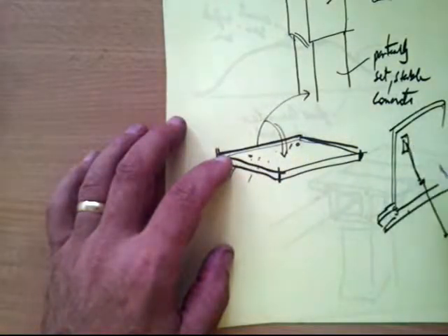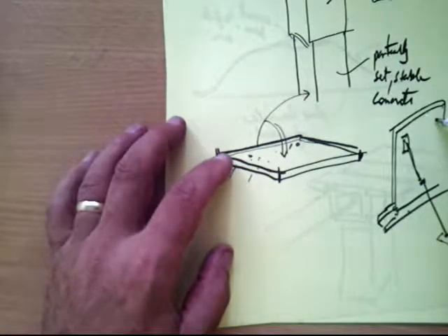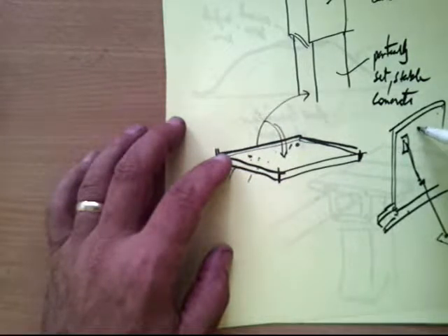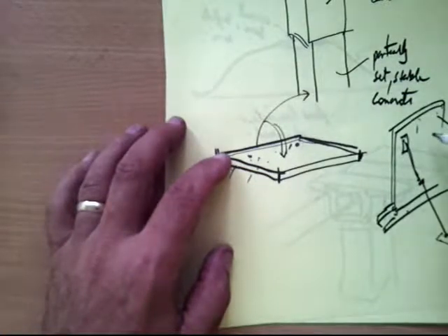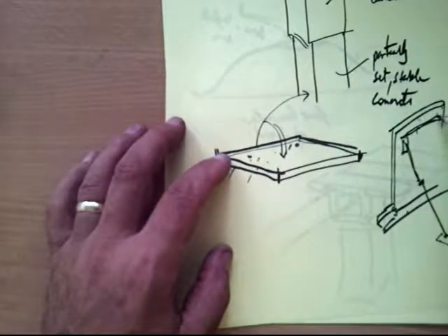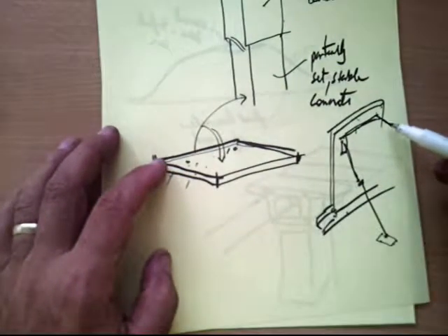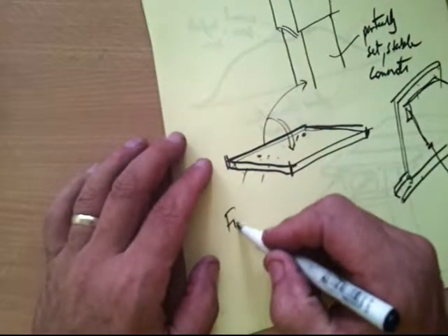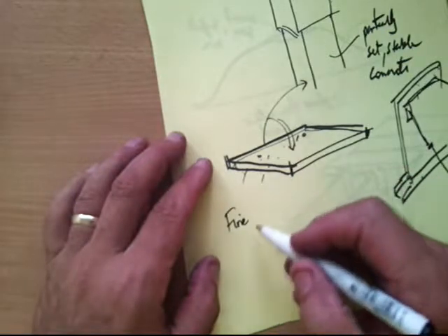Hydraulic rams will be used to hold it in position and steady it, and there'll be bolt holes that have been pre-cast into sections, so those rams can be bolted in nicely, and same thing on the floor slab. And then when all the walls are fitted together, there'll be an internal steel framework that these slabs will be bolted to, and when that steel framework has been bolted together, the whole thing is stable. These can't take very much lateral stress. They can take plenty of compressive vertical stress, but not much lateral. So the steel framework is needed, and basically they become panels that are mounted to a steel framework, which provides the structural rigidity.